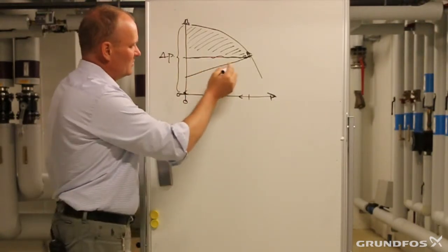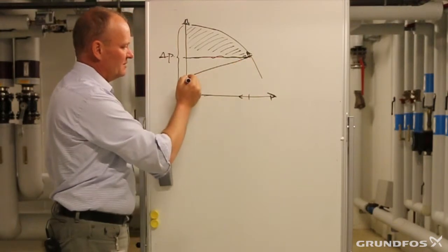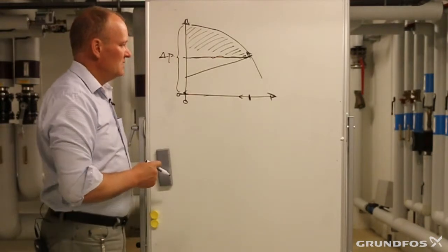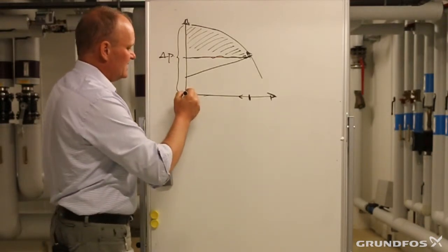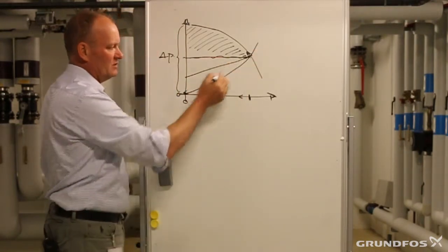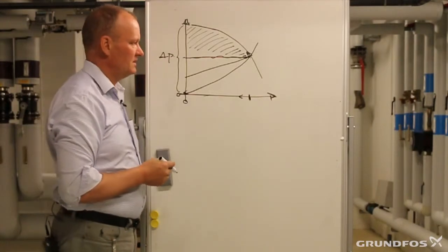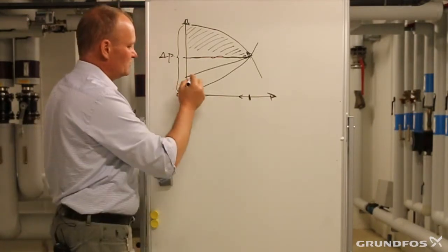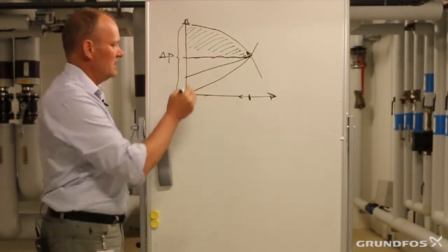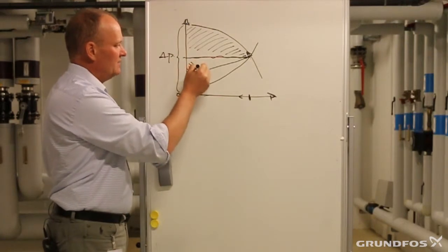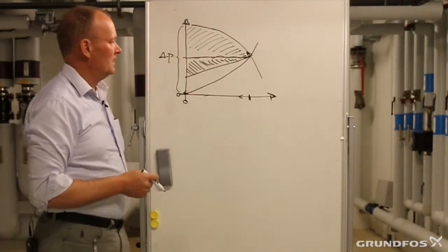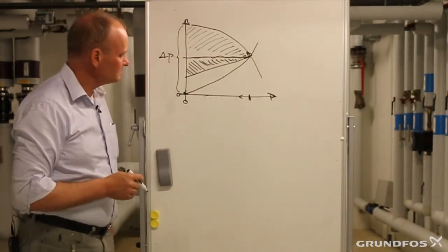When we focus on proportional pressure, you might remember that this is where we have this curve, which is where the pump is decreasing the pressure at times when the flow is going down. And this is exactly the reason for that, that we are trying to adapt to the actual system characteristic for the system. So with the proportional pressure, we get closer to the actual system characteristic, which again will allow us to save another element of energy, which could be illustrated by this area here.